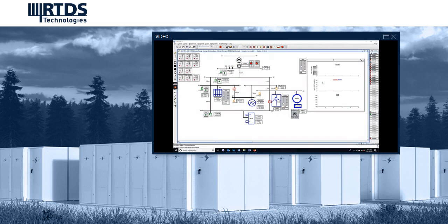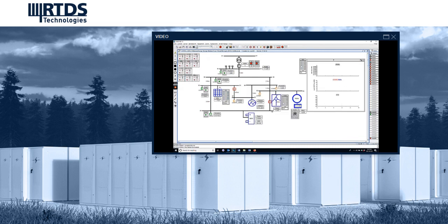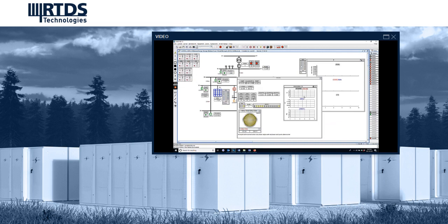Let's look at the real-time simulation model for the microgrid. Currently, the microgrid is grid connected with the PV, the diesel, the battery, the wind, and the flywheel. There are fault controls for adding faults to the microgrid. There is a load shedding control to maintain the frequency of the microgrid. There are synchronization controls for reconnecting the microgrid back to the grid after it's islanded. There are switched capacitors to maintain the voltage limits to reconnect the microgrid to the grid.